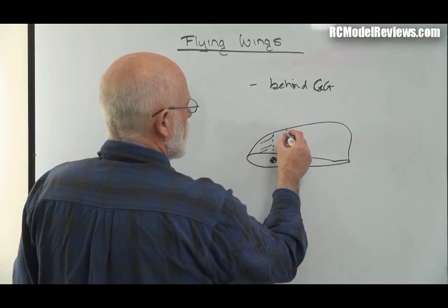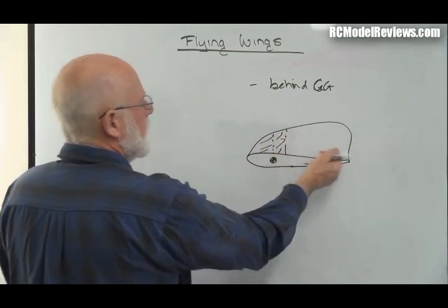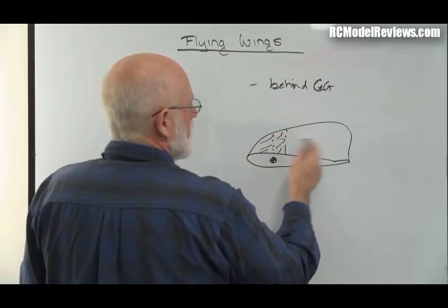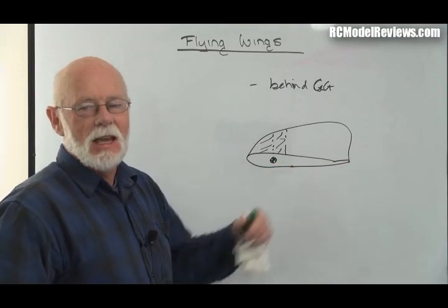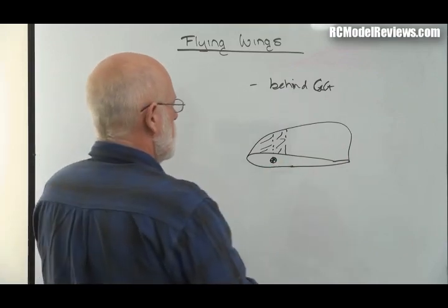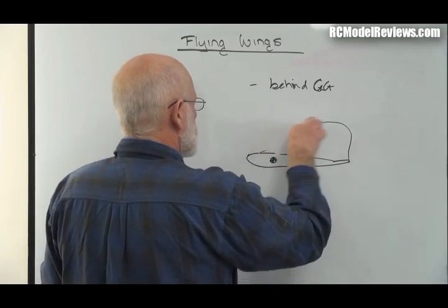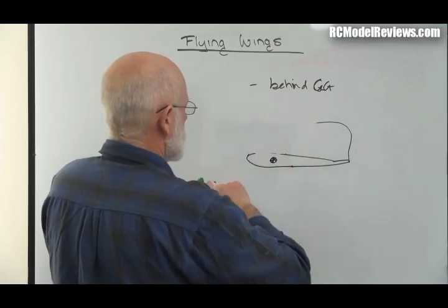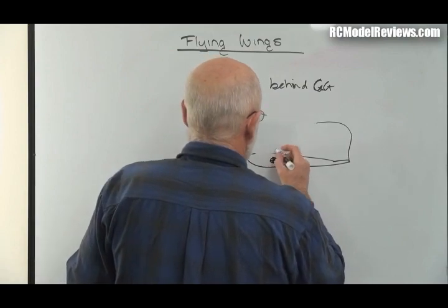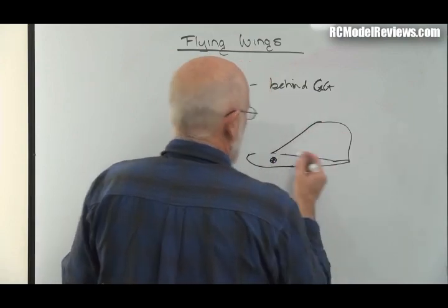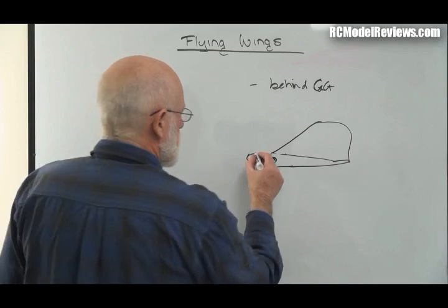So you would lose an equal area in front here. So you'll have all the drag and everything of a big fin, but you won't get the effect of a big fin because two bits are cancelling out. So generally speaking, for fins, you want to design your fin so that all the area is behind the CG. So design it like this, and then it's going to be far more effective. You don't want any in front of the CG.